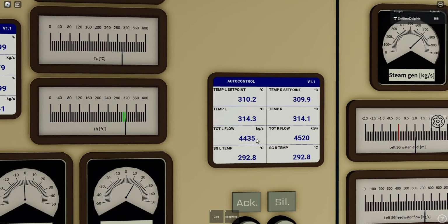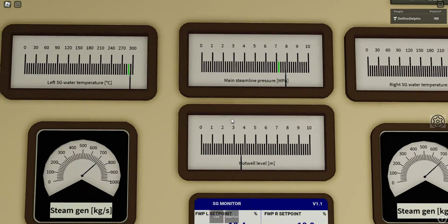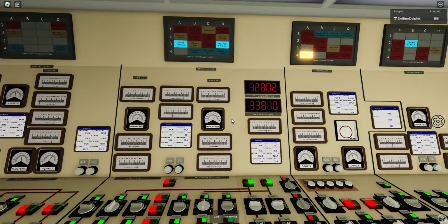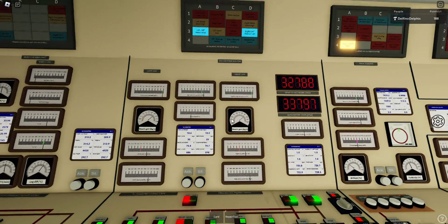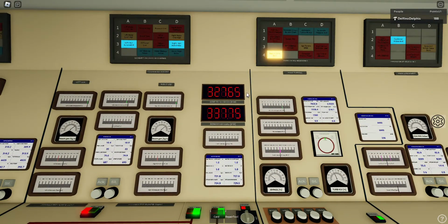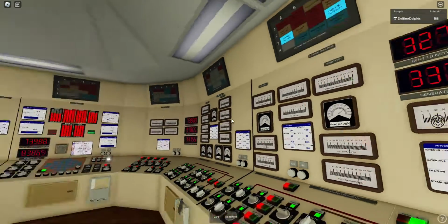So you can see it reduced by almost 10%, and now it should more or less self-stabilize. So the temperature will start dropping here now. This will reduce steam production, and this should also reduce pressure. So you can see, although it started dropping again. So I set this at 300 degrees. It rose back a little bit, but now it started to drop. Okay, more or less stabilized.